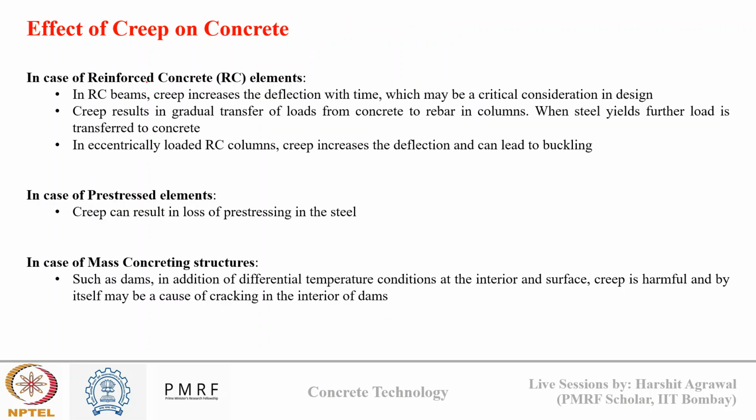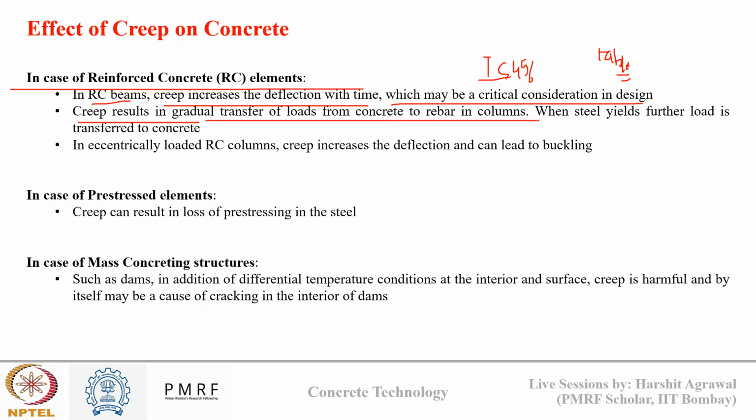Now, how does this deformation due to creep affect the concrete performance? We can see it in three different domains. In the case of a reinforced concrete sample, in an RC beam, creep increases the deflection with time, which may be a critical consideration in design. If you go back to IS 456, you will see a table where creep coefficients are mentioned, because this creep effect can be critical in terms of design.